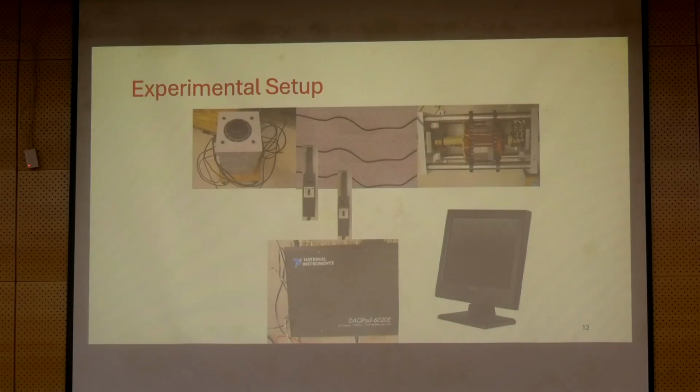So yesterday I was chatting with a couple of you, and oscilloscopes nowadays have storage capability, and most of them are 8-bit. So you have to check whether 8-bit is sufficient or not. But any low-cost microcontroller might be able to get you data acquisition at a reasonable bit depth, like 12-bit is quite common, right? So you should be able to do that. ADC count is quite easy. So you can use that to acquire data. So you may not have to invest in expensive equipment as far as data acquisition is concerned. You might already have it. You might buy low-cost components as well.